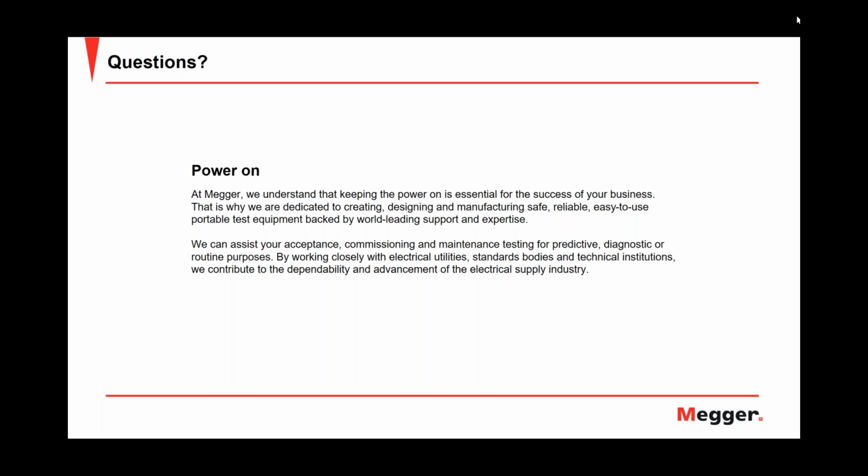So overall, it's a preferred method. You can see that also when you do a test and have a test failure, which can happen. Typically, the fault resistance when you did a VLF test is lower than when you did a DC test. So it's already easier to fault locate typically when you had a VLF test before than when you had a DC test before.